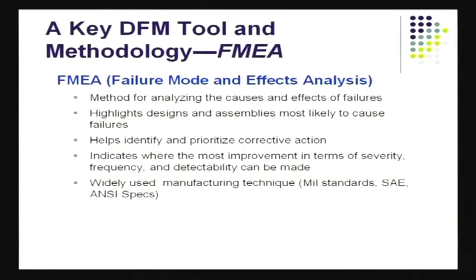Then, of course, you move slowly into FMEA. FMEA is really failure mode and effect analysis. What is this approach? You try to predict failures, and you look at, first of all, the different modes by which it can fail. What are the different ways a disk drive could fail, for example? Then you try to identify what would be the impact if that particular thing failed, and what is the likelihood for it.